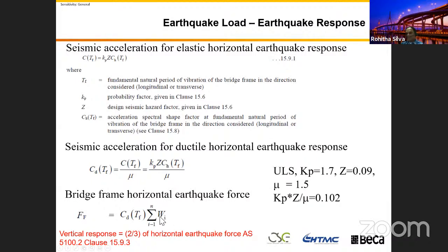That's why we can straight away multiply this one by our weight W, that is in kilonewton, right? We get the percentage of gravitational acceleration. That means it is already divided by g. That's why we can use the weight in kilonewton in here. Otherwise, because when I use the word acceleration, you will change that weight to a mass divided by g again. It's already taken into account in here.